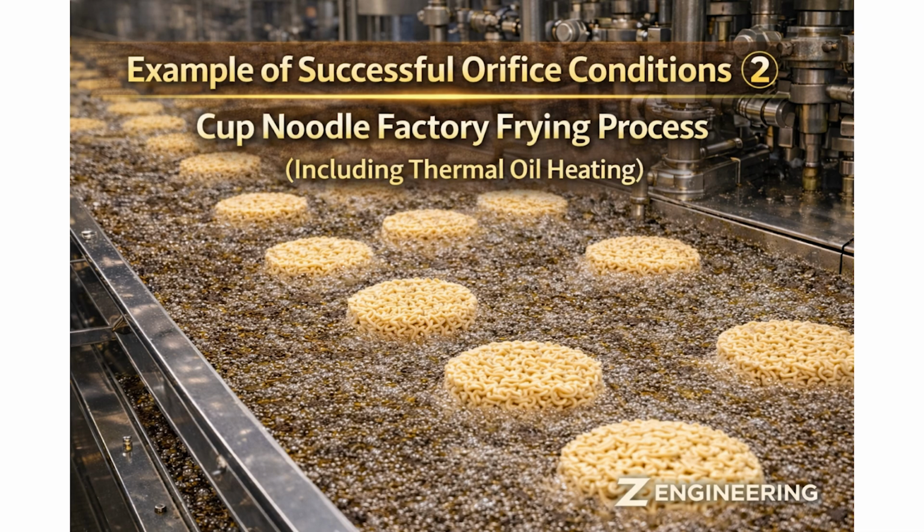The same is true for heating processes using thermal oil systems. The required heat load is determined by the operating conditions. Steam consumption remains within a predictable design range. Differential pressure also stays stable. When these conditions are satisfied, an orifice trap can work properly.